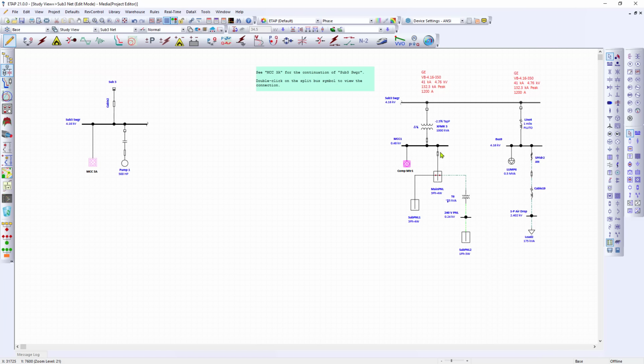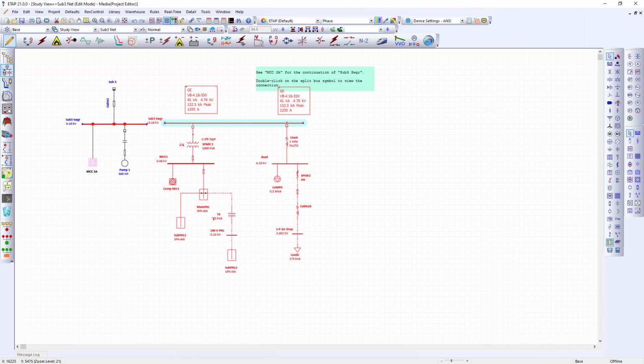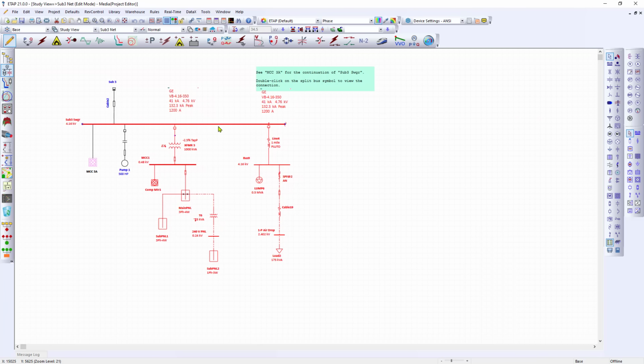And in this example, I've decided to visually move and isolate all the connections that have single phase equipment. So from this portion of the bus, I have tap outs that go into my panel boards in single phase, and I just wanted to move it off to the side just for visual clarity. And you can imagine if this was an extremely large project, how these tools would be very beneficial. And if you change your mind and decide you want to reconnect, very easy. I can just touch the two endpoints together and it automatically reconnects for me.